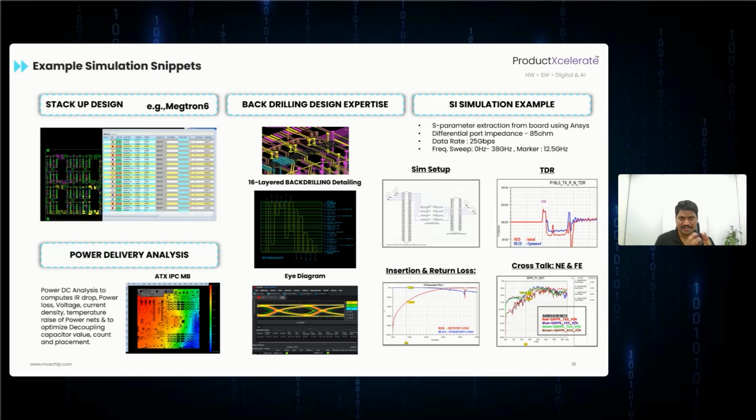High density interconnect PCB utilizes microvias with laser drilled holes with diameters as small as 50 to 150 micrometers. Blind and buried vias are holes that don't go all the way through the board, but go to a specific layer in dense boards.